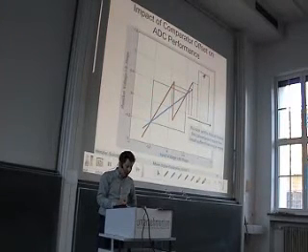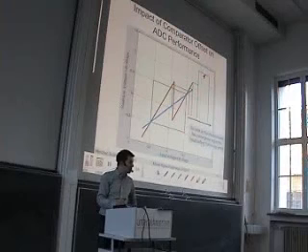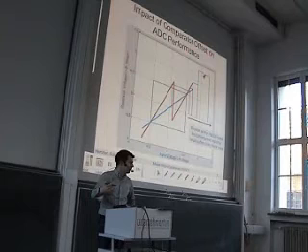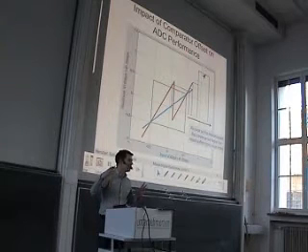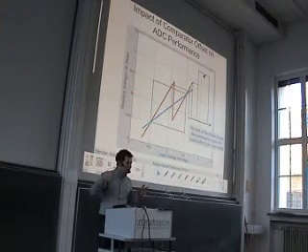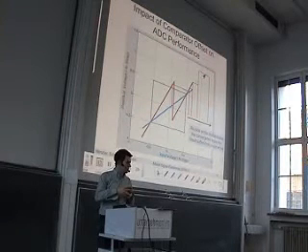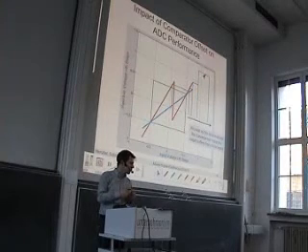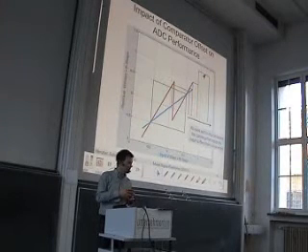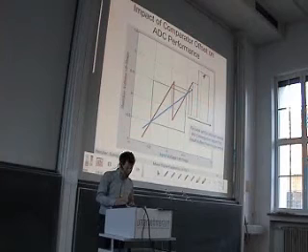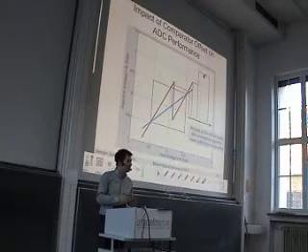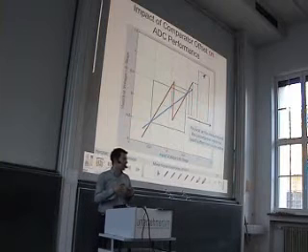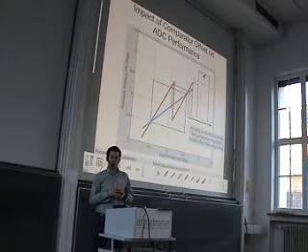This means that the residue, which is the quantization error, becomes larger and larger. So what we actually want is that the quantization error is reduced. As we have this gain factor of 2, it is not reduced to 0, but it should stay inside this box. And if we leave this box once, then it becomes larger and larger. So obviously the algorithm doesn't converge anymore.